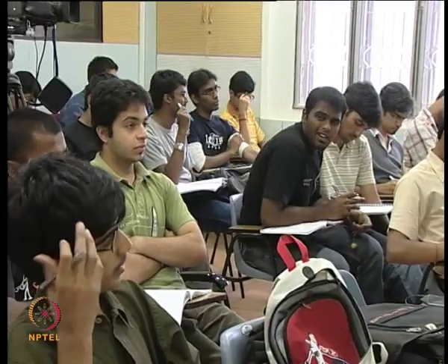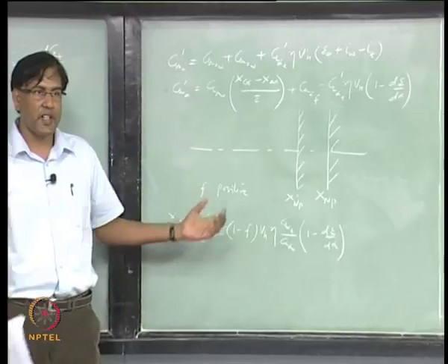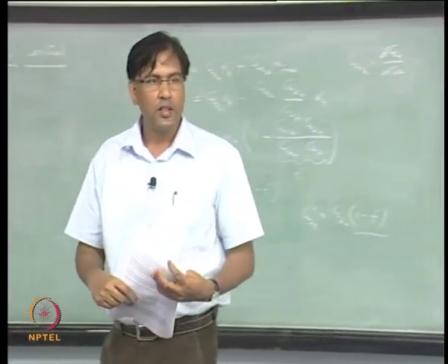Then we said it will be till the neutral point. No, neutral point is the most aft. Now it's going to depend upon this also. If the elevator is free, then x and p prime is the most aft limit of the CG, right?